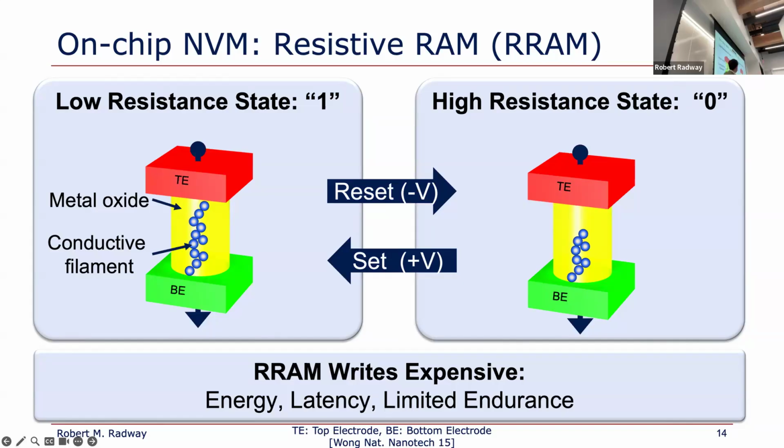So there is this idea of feature size, it's called F in scaling. So this is a 4F squared memory in its best implementation, where you have the metal pitch for the size of the square times 2 for the space. That's the maximum density that you can fabricate it. It's a very dense memory technology. SRAM requires 6 transistors. Each of those transistors is many F. So SRAM is something like 130 to 160 F squared. So many, many times worse in terms of its density.